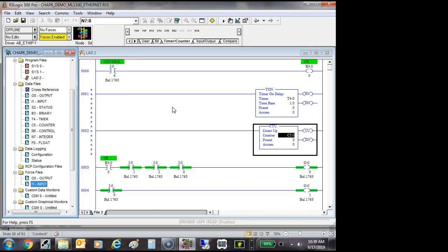Well, what you can do is you can password protect the actual CPU. I kind of say it's like leaving a key in it. Yeah, that's exactly right. Everybody doesn't have access. Most of your PLCs, we just don't put them out there. For one thing, you've got to have a computer that's got the application on it, so you can't go out there with your smartphone and connect to it. You'd have to have the computer with the application installed on it. In most companies, they should password protect the CPU. If they password protect it, then you can't do it anyway.